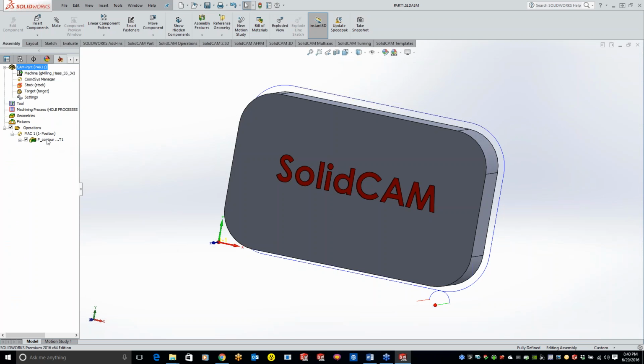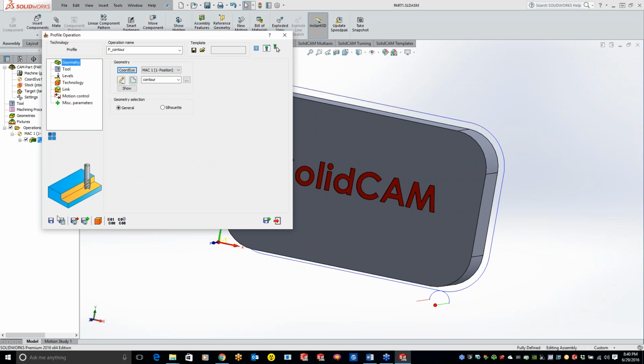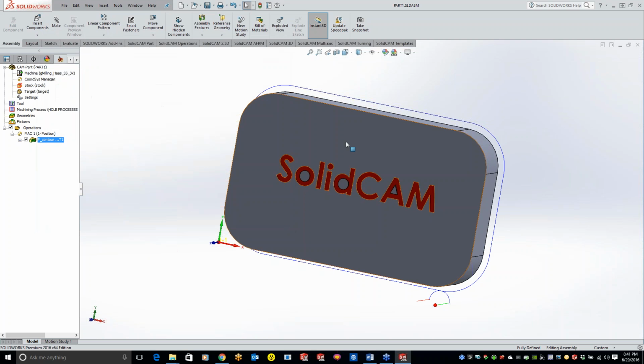But if you put 10, 15 hours into programming this part and you just want to ensure 100% that it is going to be there when you close out your computer and shut down, what I would do is go to your very last operation in your tree, open it up, and click the Save and Calculate button. That will 100% ensure everything has been saved and updated, and then you can go ahead and close out of that file. That is the easiest way to save.